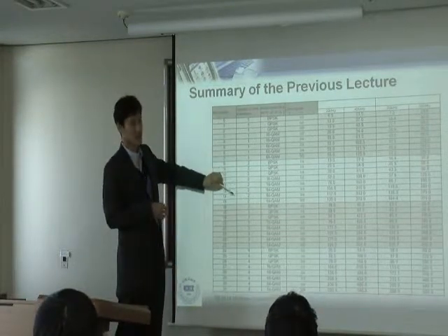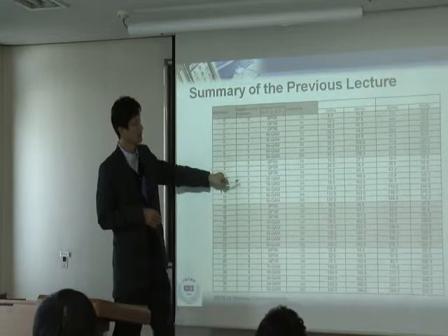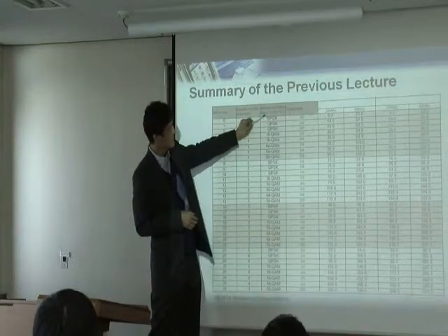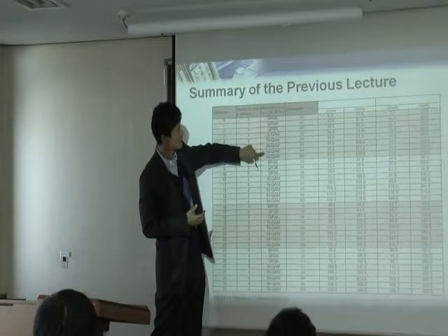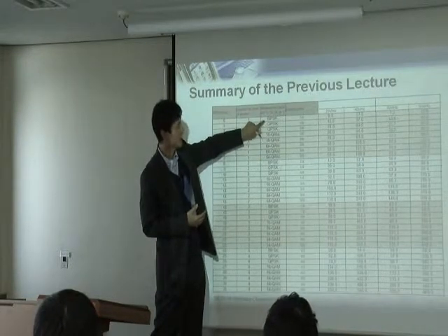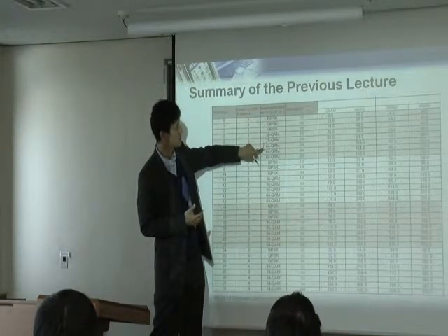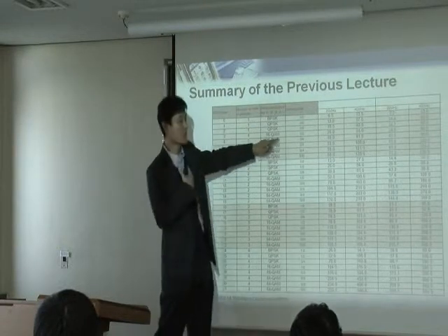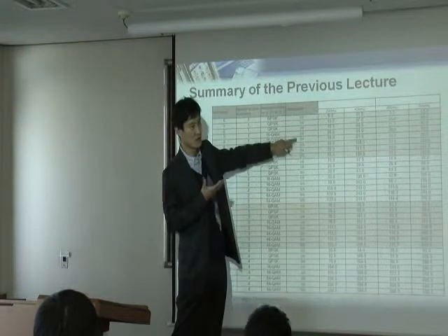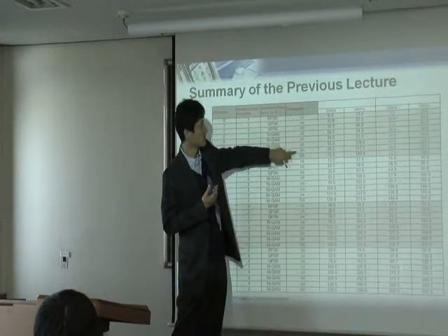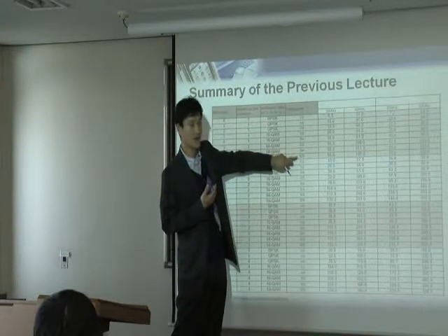Here in the 802.11 wireless LAN case, they show you the modulations they use in the spec: BPSK, QPSK, 16 QAM, 64 QAM. They also clearly define their own coding rates. It's pretty clear: half, 3/4, and 5/6.